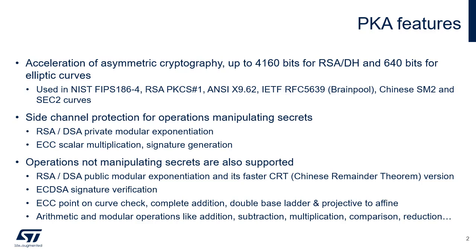The list of supported operations are described here. Modular exponentiation for RSA decryption, scalar multiplication, and signature for ECC are protected against side-channel attacks. Those operations are used when manipulating secret keys.